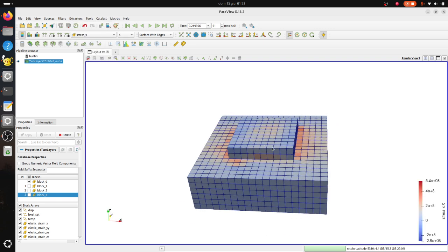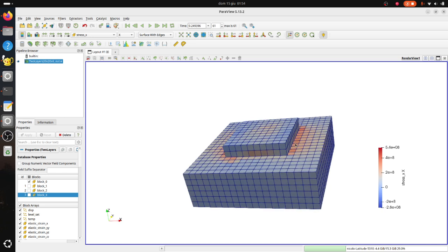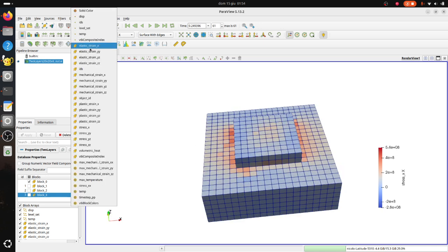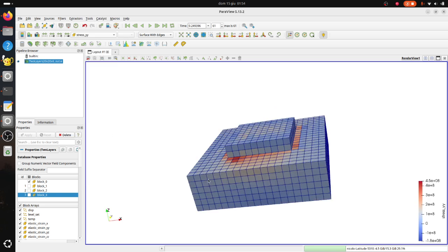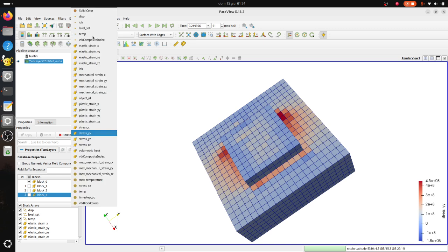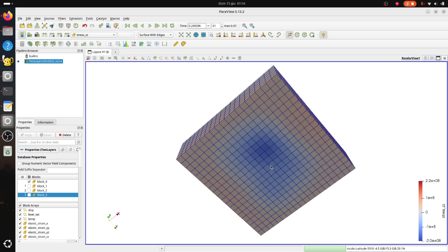Yeah, so the residual stress, if you look at the x-axis, because my scan was along x, the stress induced by the heat source ahead of the heat source is compressive. But then, because it induced plastic deformation, when the system cooled down, it created this peak of tensile stress just next to the layer. And if you look at the YY, it will be tensile mostly in the direction perpendicular to Y. Okay, while the ZZ, as expected, will create this kind of compressive stress at the bottom.